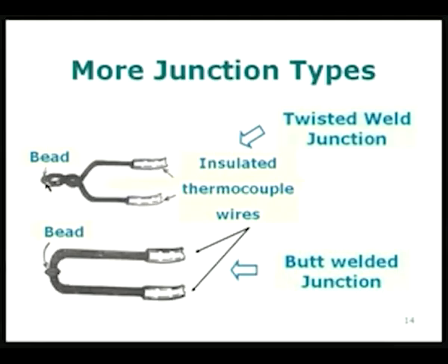So, what is normally done is we charge a capacitor to a high voltage, and then the two terminals of the capacitor are connected to the bead here, and you close the switch, immediately the charge in the capacitor is going to be discharged through this material and will hit the material locally, and it will form a nice weld to form a nice junction.